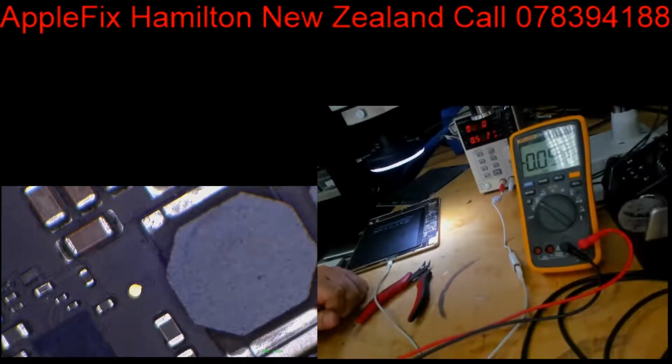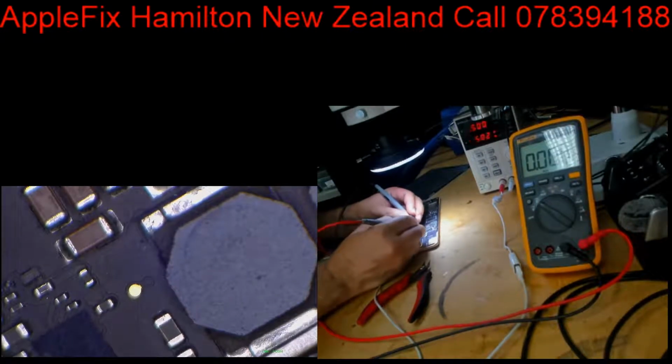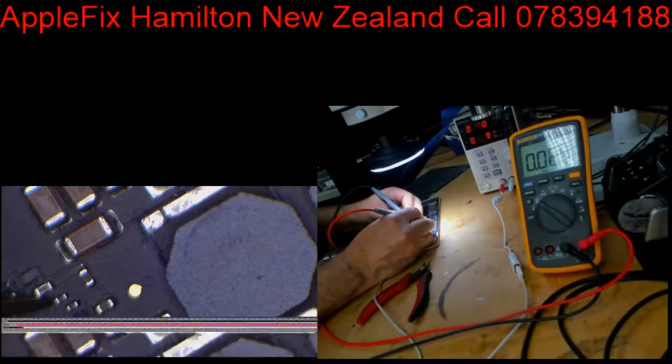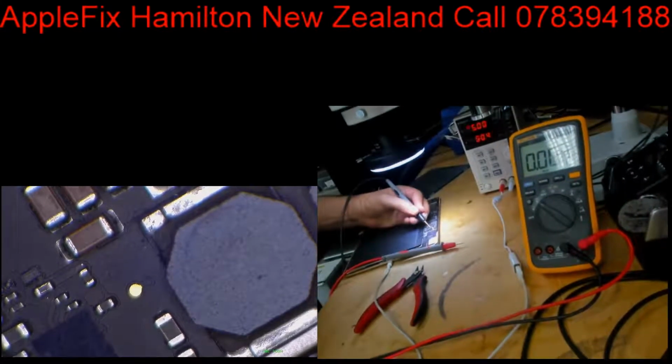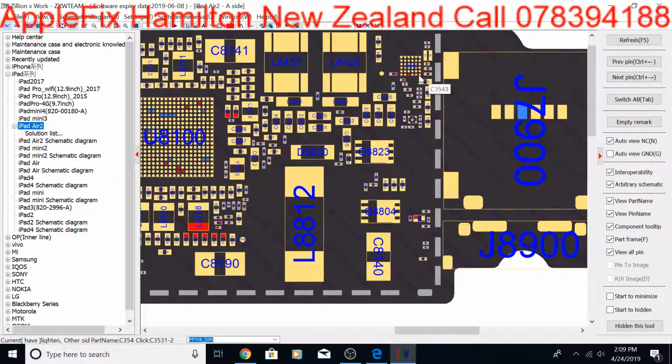Now, instead of going back and forth, let's keep checking from here. So now what are we getting? Nothing here. So this is not connected. 3 volt here, that's fine. We are getting 1.7, that's right. Because of the knowledge, I know this is what it should be. So see guys, let's check this one here, second from here. I'm not getting it, it's just dropping the voltage down.